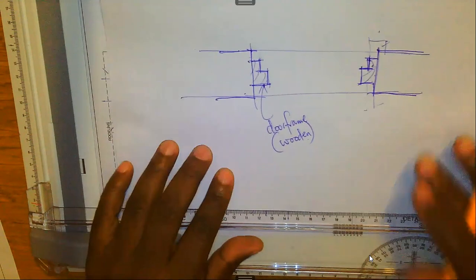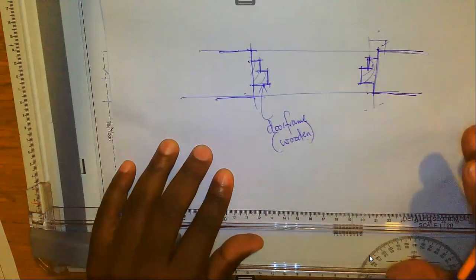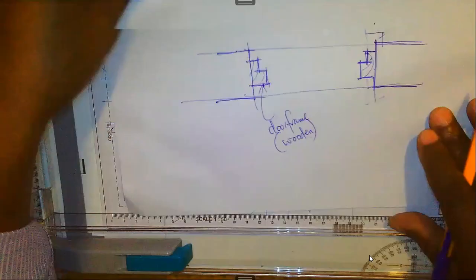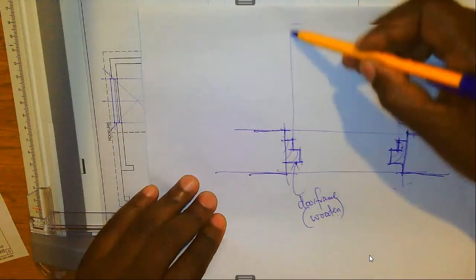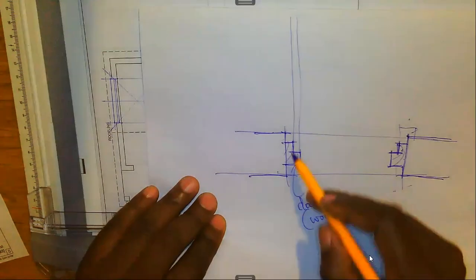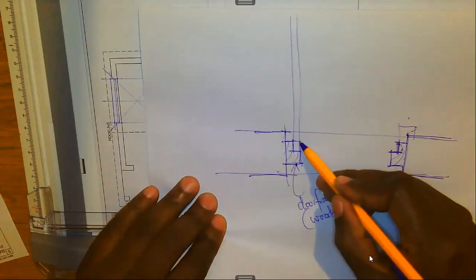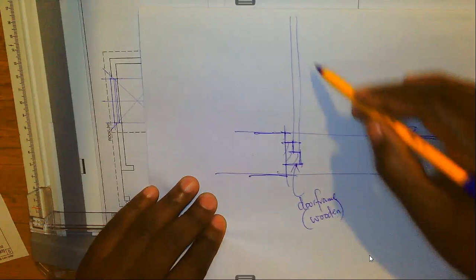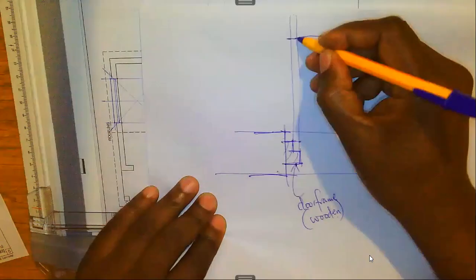Right, this is how I want you to do it, okay? Right, there are so many ways that are employed in terms of drawing the door and representing it in terms of opening and closing. Right, normally on a floor plan, the door is represented in an opened position. So draw this line like that, right? And also project this line like that, right? At this point, you close, okay? Right, you take your compass from here to this point, then you describe an arc, right? Then you close that part. Then this is our door.